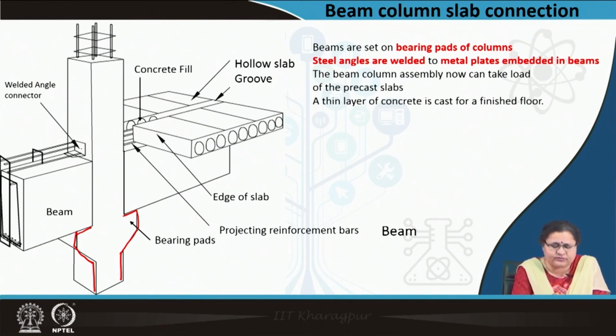Further, the beam has a welded connection with the column, making it a very strong joint. Thus, whatever load, some 30 feet, 25 feet, 40 feet, the entire load is being borne by this and is transferred through the column to the foundation. If that is not done, the structure or the system will crumble.